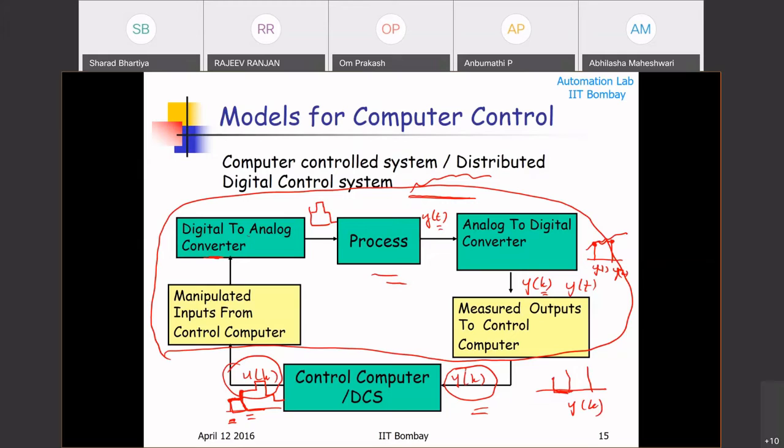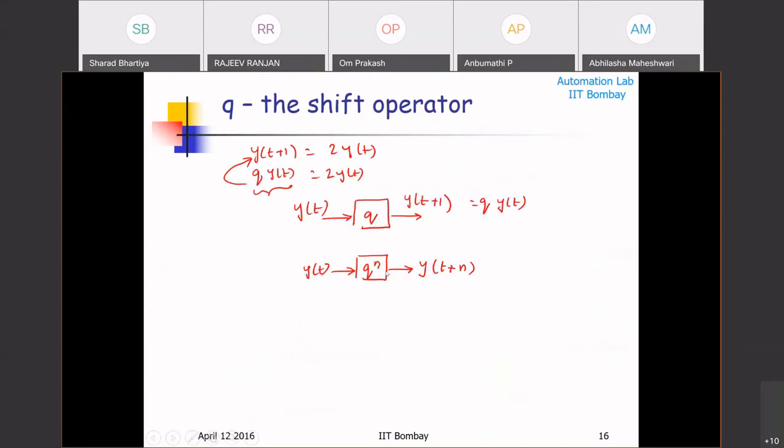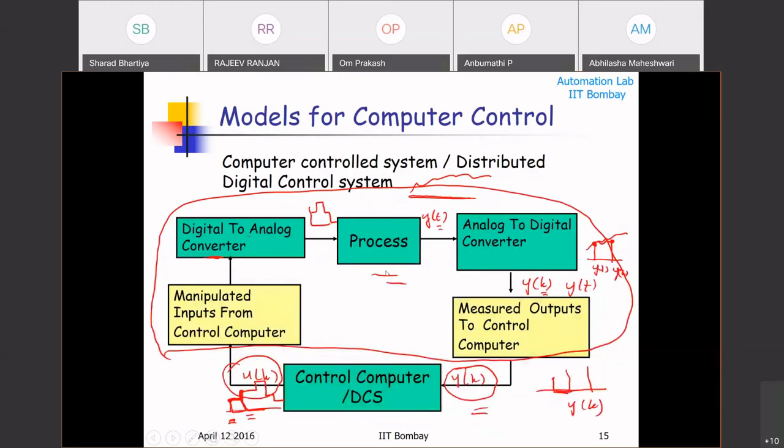In this case, now I was trying to, when you use u of k and y of k, we always think that, oh, it is between the process, u of t here and y of t here. What we forget is that there is a lot of signal conditioning, and really it is all that gets caught up over here. So when we model u of k versus y of k, we have all the signal conditioning elements as part of that model that I have. Okay,